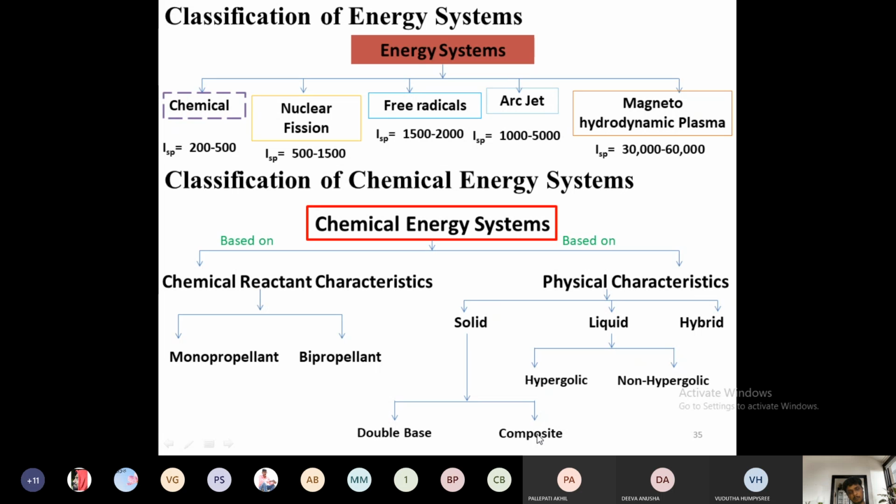What is double base now? Double base systems are nothing but monopropellants, like nitrocellulose with diphenylamine stabilizer and nitroglycerin explosives. Certain explosive compositions will be mixed. Therefore, it will obtain a double tone of energy. So this is called a double base propellant, which is nothing but a composition of nitrocellulose with diphenylamine stabilizer and nitroglycerin explosive. Sometimes it may contain non-explosive plasticizers also, such as diethyl phthalates.